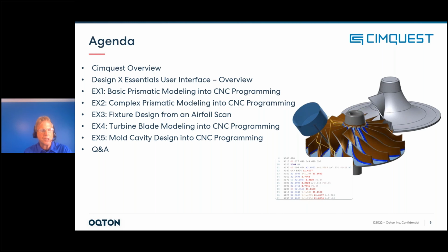Then we're going to take a little detour from CNC and talk about fixture design. I have the scan of an airfoil, and we're going to discuss how we can utilize the airfoil scan to build a riser block underneath the airfoil to support it for perhaps an inspection or a CNC programming application.